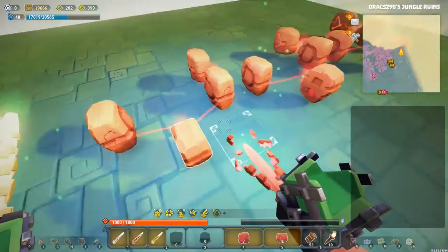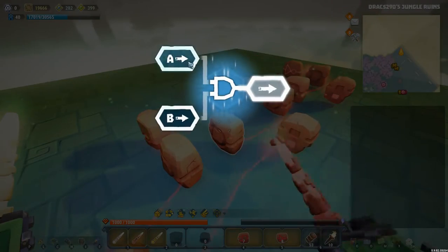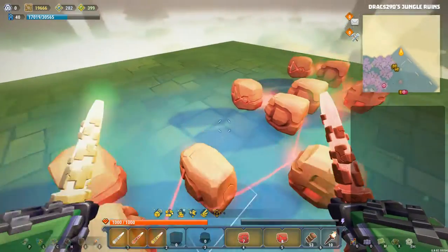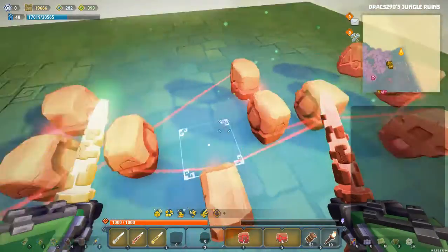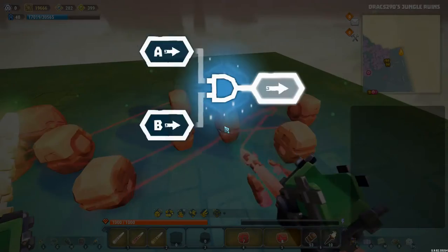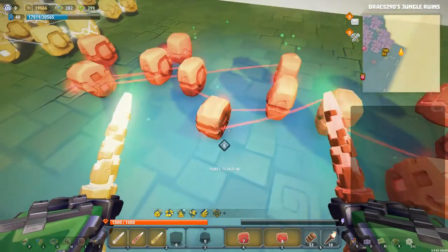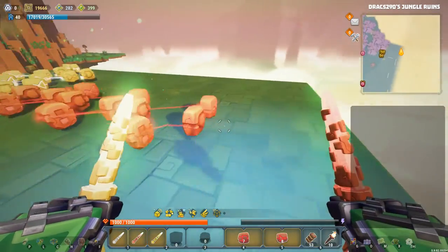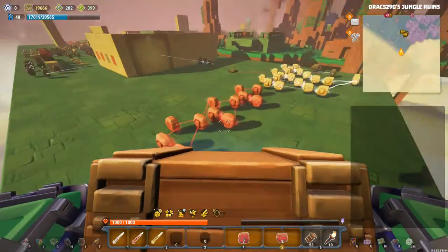So the latch goes into the A side of the AND gate over 1, and it also goes into the NOT gate over 1, just like that. So that's the first into the second. Now we're going to do the second into the third. So here we go, we're going into the A side of this AND gate, and we're going into the NOT gate over there.